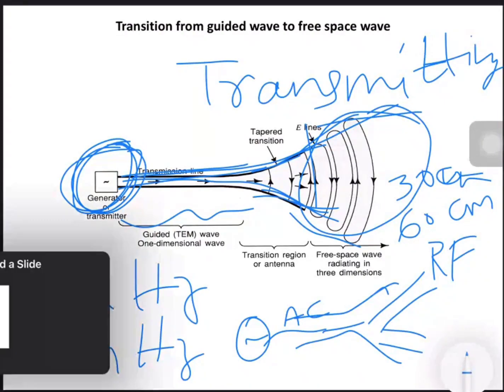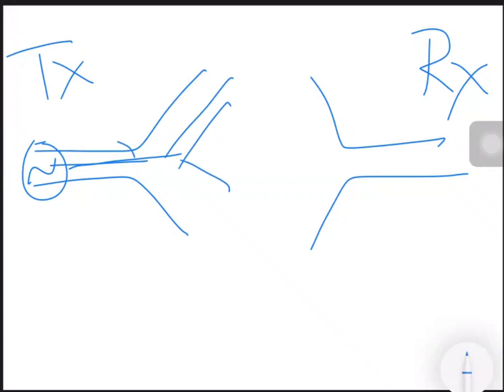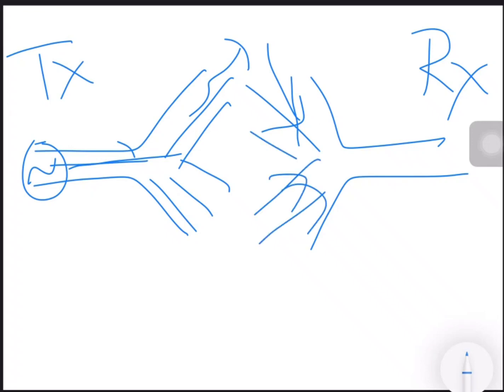And on the receiver side, this is the transmitting antenna which is there on the transmitter side, and this is the receiving antenna which is there on the receiver side. This is transmitter and this is receiver. The signals that are given from the microwave source will propagate in the waveguide structure of the antenna, and are allowed into free space. This is the RF signal. And the important property of a receiving antenna is to capture the signals which are available in free space. So this antenna on the receiver end will capture, or acquire, or absorb the RF signals which are available in free space, and that allows the propagation to the output. So here we'll be measuring the output power of an antenna.